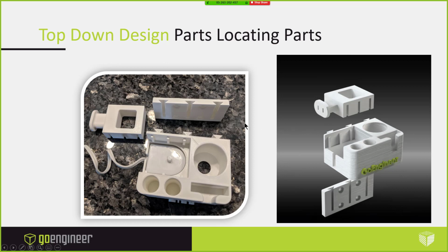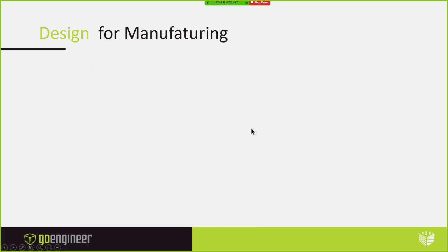This is kind of a top-down design. This is kind of an all-in-one for this design for manufacturing. So we're taking advantage of making parts reusable. In this wall plate, taking advantage of symmetric and pattern parts, and then reusable design library parts like dovetails, making your parts easy to manufacture. So you can't install this backwards or upside down or any way, and it's pretty self-explanatory. There's a fillet here to help you align it. If you spun this around, it's definitely not going in there. So that was the idea when I designed this.